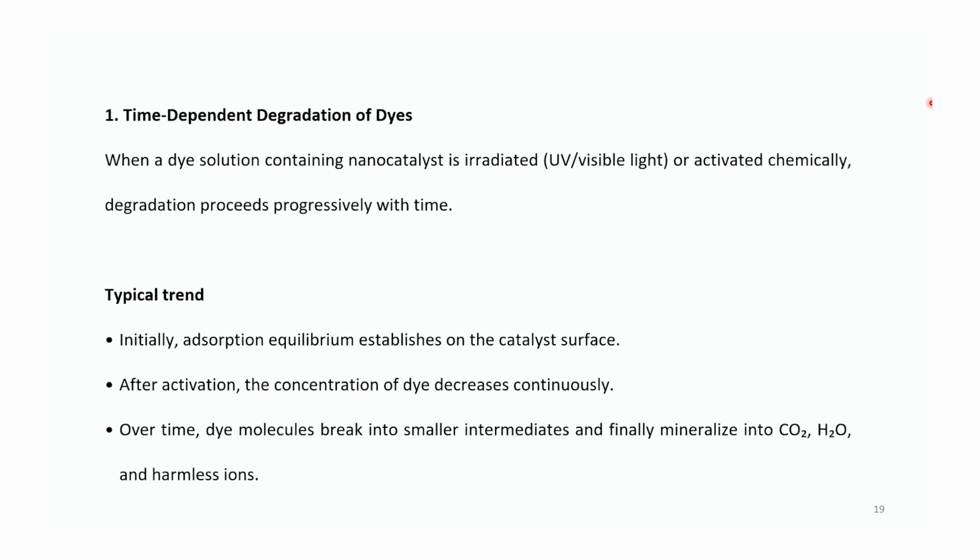When a dye solution containing a nanocatalyst is illuminated or irradiated by light, either UV or visible light, the catalyst gets activated when light passes through it and the degradation process starts. That degradation process proceeds progressively with time. As time passes, degradation continues. So the typical trend is that initially the adsorption equilibrium is established on the catalyst surface.